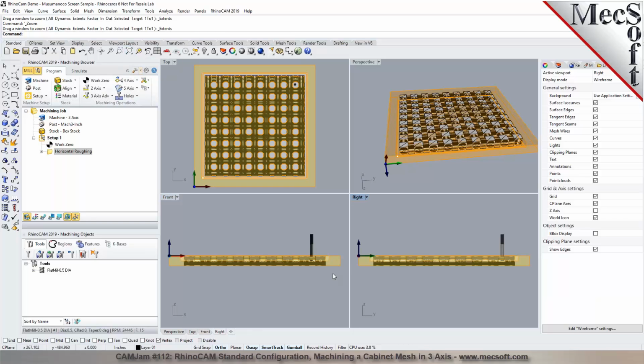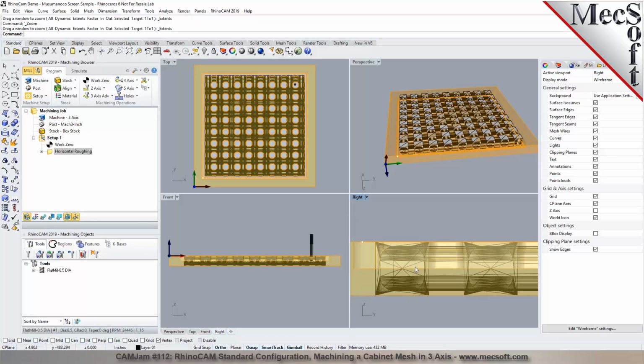Okay. Now, when you do this, you can do it in more precise locations. I'm going to show you basically how it's done. Basically, you just want to run a solid or a surface through here that passes through the part and through the stock. So that when you do your finishing operation or your roughing operation, it sees that part and it'll go over it. So it'll leave you a tab there.